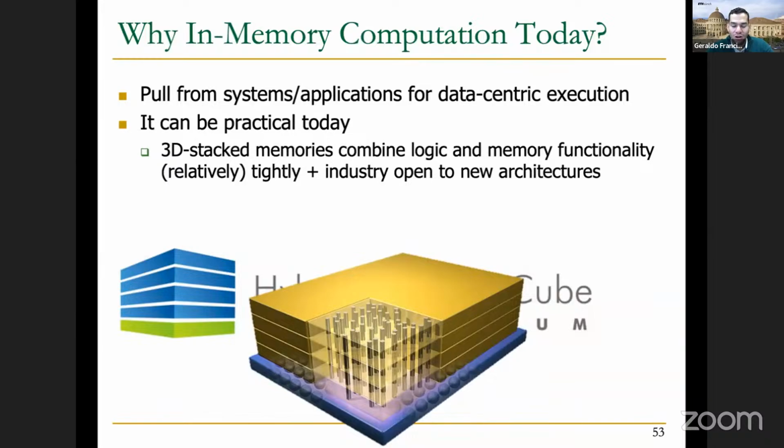And you also have a push or opportunity coming from the technology. For manufacturing purposes, designing chips where you can have compute and memory in the same place is quite challenging, because historically those manufacturing processes have been optimized for different purposes, which are contradicting to each other. However, due to packaging advancements over time, like 3D stacking, now we can design computation in its own manufacturing process, and design memory in its own manufacturing process, and then use these advanced packaging technologies to glue them together. And so now we have a way of realizing those processing-in-memory architectures in a more feasible commercial way.